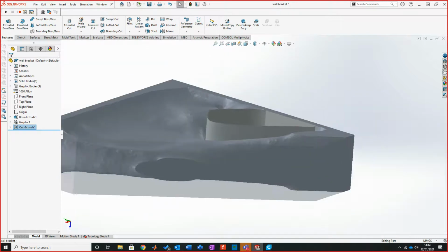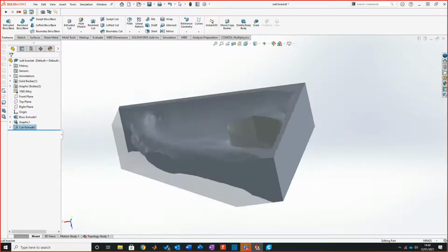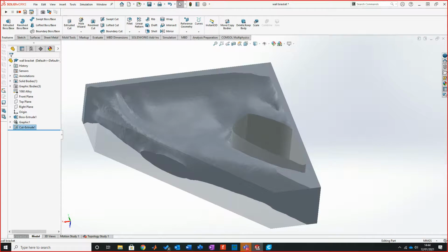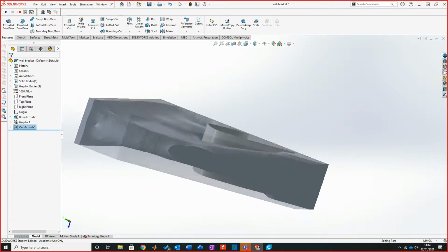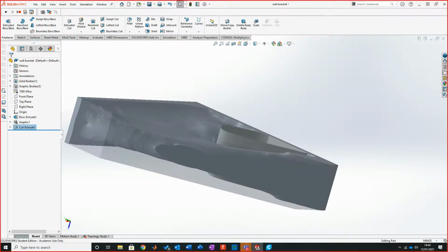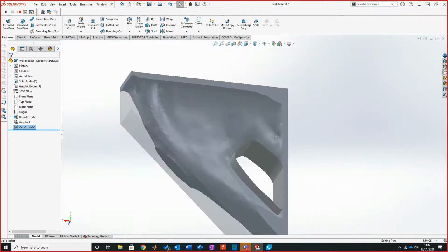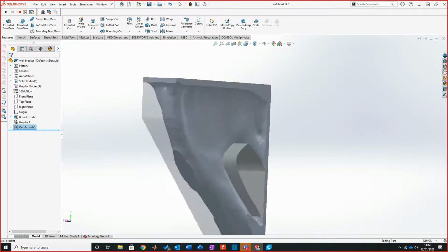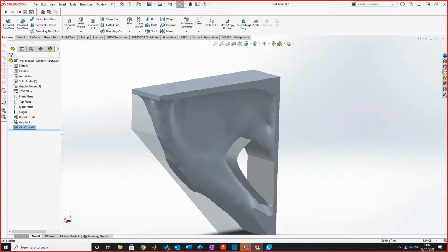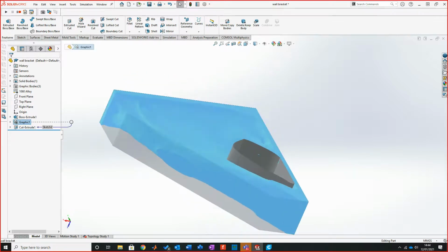What I then want to do is look to cutting these bits back. Now the thing is, the way that this is designed and the way that something like a hip is loaded, it wouldn't end up looking something like this. It would end up looking a bit skinnier, if you will, on key particular areas, and then we could modify that even more. But I think the first thing is for you to establish geometry, because we can do millions of things with this. It's like the graphic itself. I can export that and put that straight into ANSYS and test it in that condition.